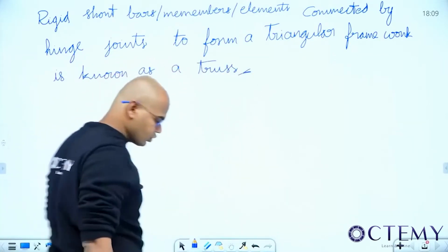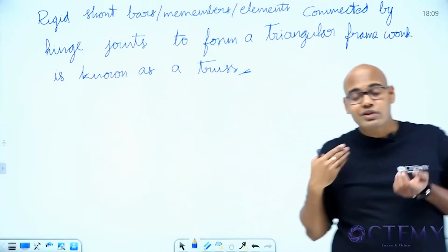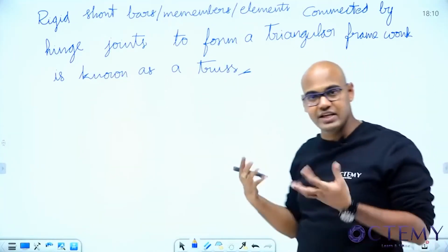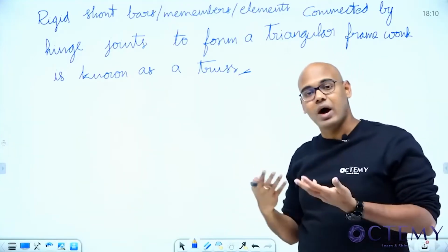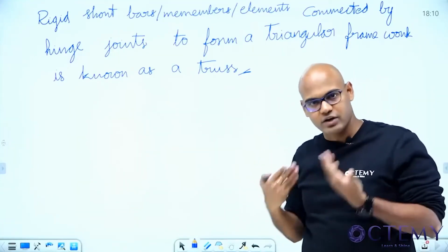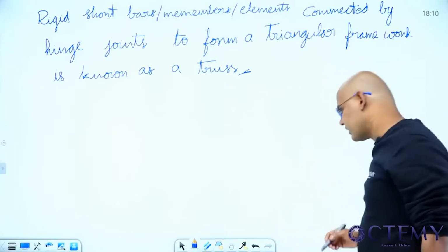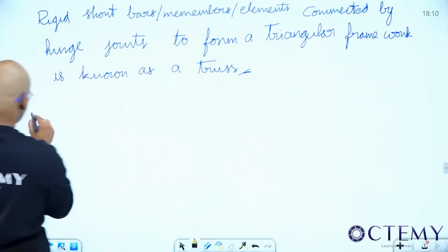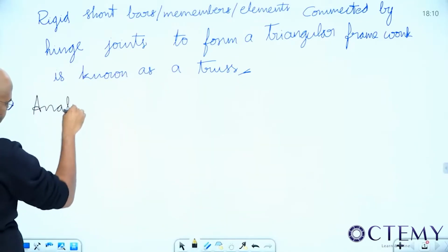And I have also told you that trusses will have only axial stresses. The members of the truss will not have any bending or shear stresses unless they are loaded on the members. Why, and all, I will show you. Okay, so now the target for us is what? Doing the analysis of these trusses. Analysis of trusses.